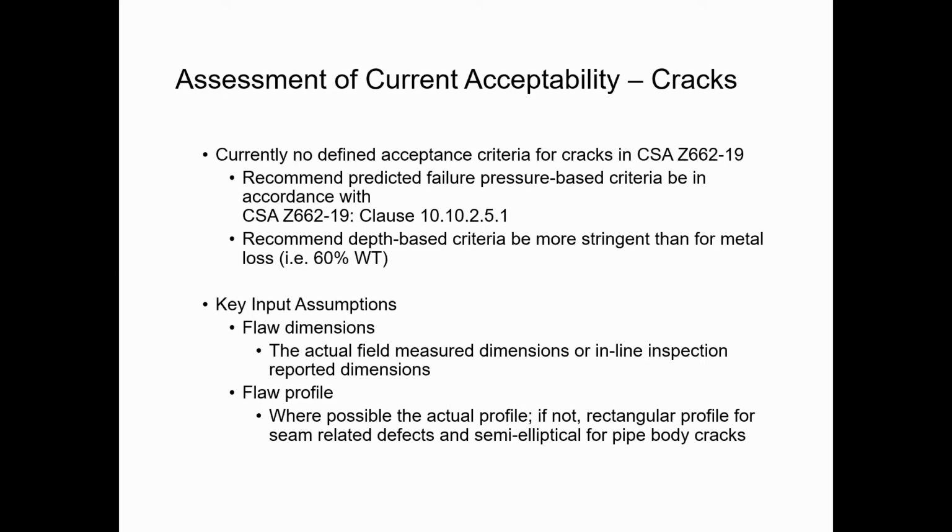Some of the key input assumptions for cracks: the flaw dimensions, the actual field measured dimensions. This is one of the things that with our clients, we deal with a number of excavation programs that they do. The more that you can do to have your field NDE vendors provide you actual flaw profiles will allow you to make more informed decisions about repairs, as opposed to them just giving you a maximum depth and maximum length, because it's unlikely that they're at that maximum depth for the entire length, so you'd be making very conservative decisions.